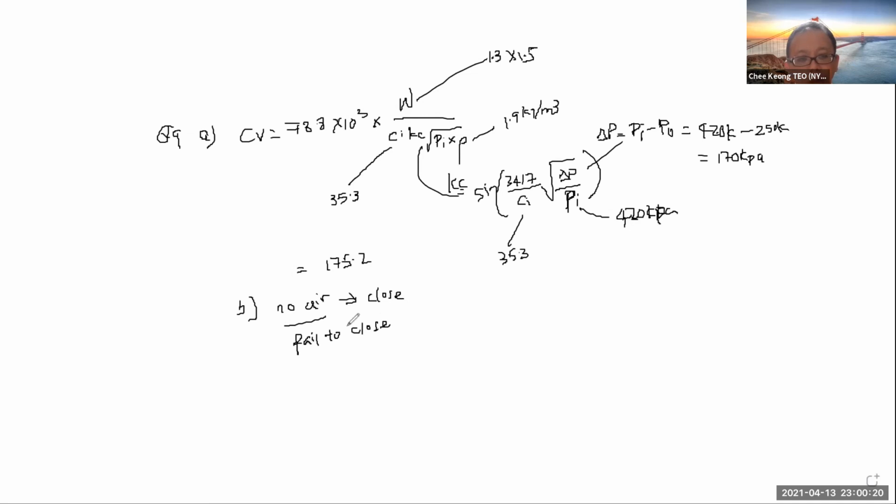So this is a fail to close kind of valve that I'm looking at for safety purpose. Oh, so it should be fail to close because, what's the reason? Because we do not want steam to come out to hurt someone. Right? So that is the design consideration.